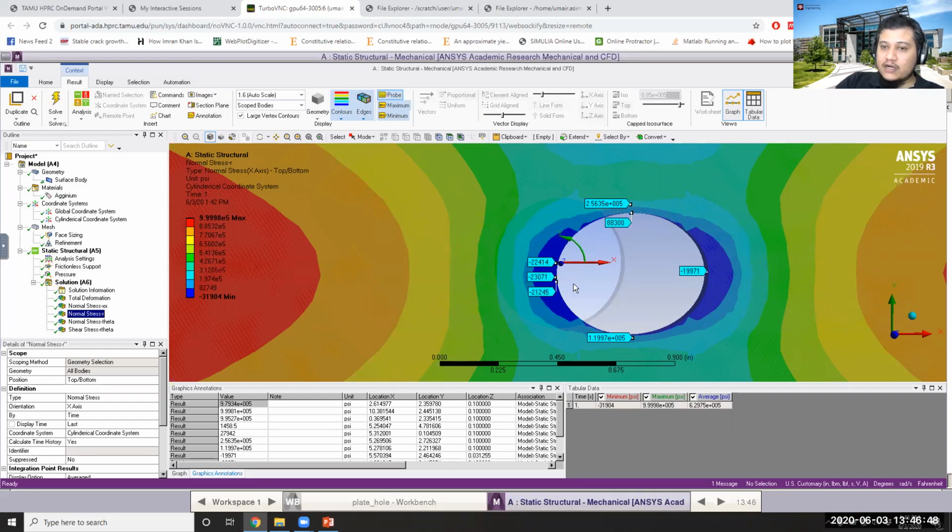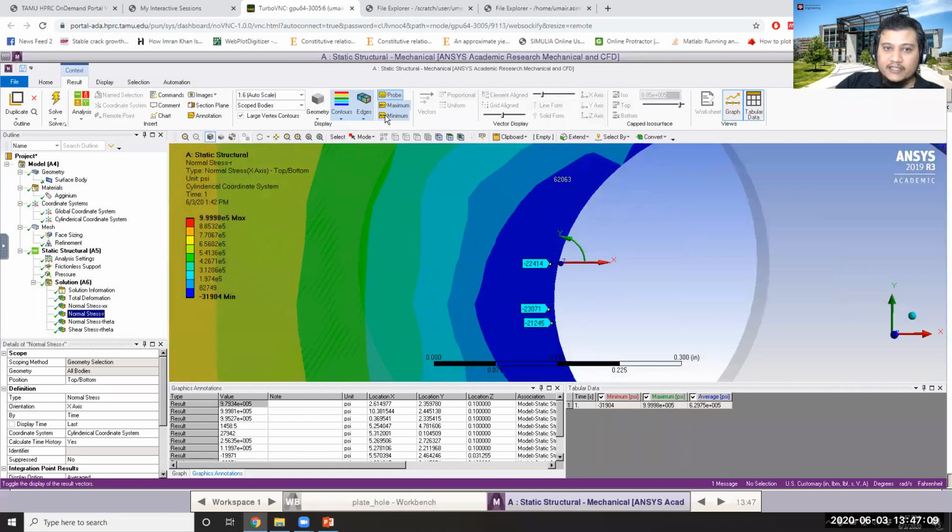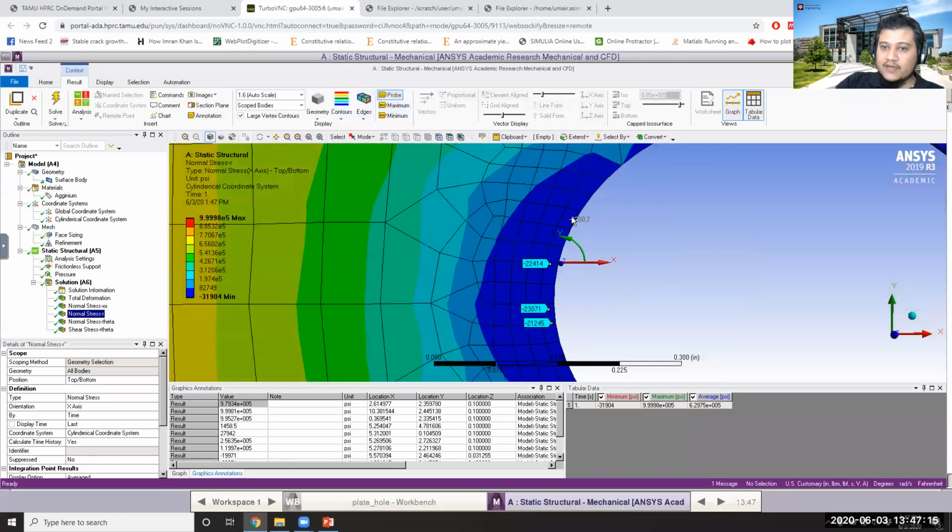But that difference is not such that you cannot still make some comparisons. The comparison is that the value of stress is very small very near the hole. This is what I was talking about, that most of the things are happening around the hole, and these values are only calculated at each element location. If I plot the elements as well, the value of stresses is supposed to be calculated only within each element. So if you want a better resolution around your area of interest, you need to improve the mesh around it so that it resolves the values near those regions better.